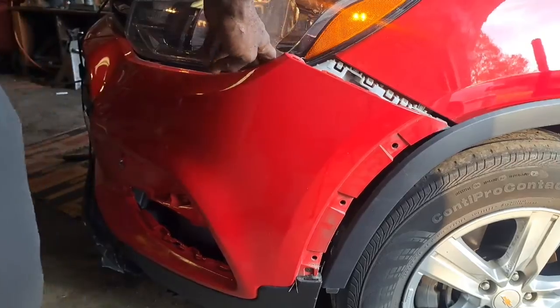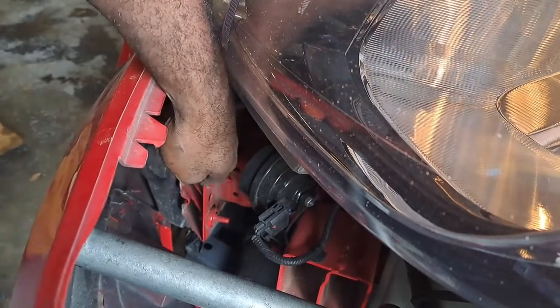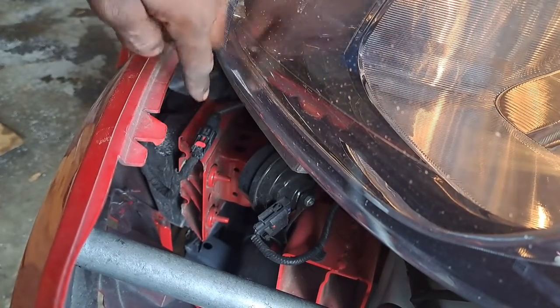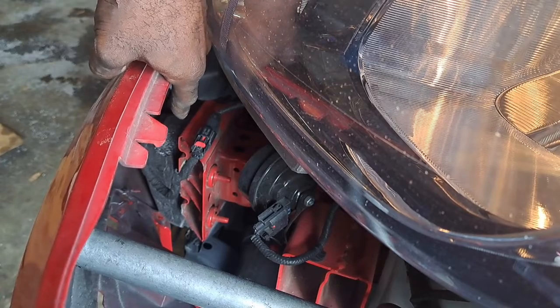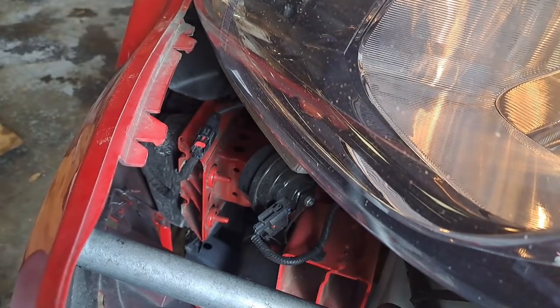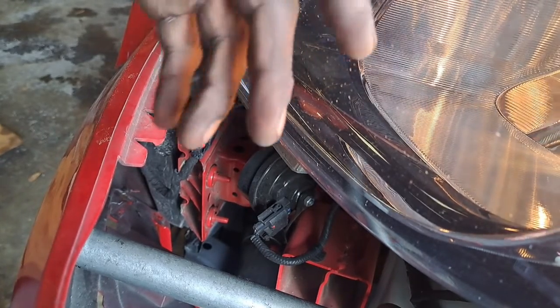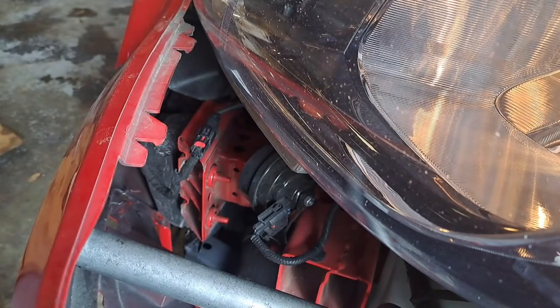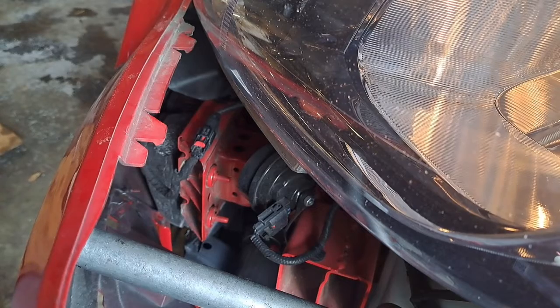I can just get in here now. I don't have to go much further. This is our connector that's going to the ambient air temperature sensor. So what I'm gonna do is pull my PID data back up, look at the live data, and pull up the ambient air temperature sensor, see if I can manipulate or change that. I'm gonna isolate this.